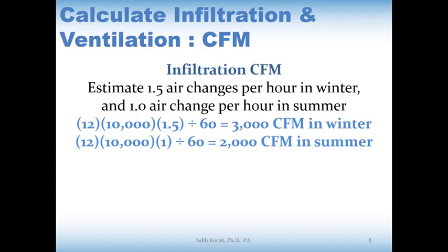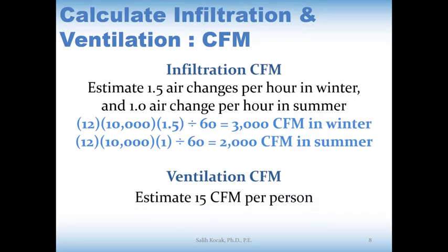So now we are going to calculate the ventilation, and we know that ventilation is needed for places, especially well-sealed, tight buildings. We said that we have to assume a minimum of 15 CFM. If something else is given to us, like for the school case, we have to use those numbers. Your book has a table that provides different numbers for different building spaces.